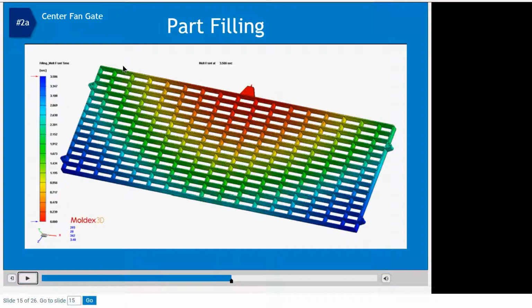Now we all know, if this cover is over, let's say, a safety hole or whatever, we have some mounting holes to put this grill over some safety area. So if the material is fiber filled and you have to have certain strength, the fiber orientation in this side versus that side through the fill pattern and through the ribs is really different. And as you know, fiber-filled materials shrink differently in the direction of flow versus perpendicular to the flow. So you're ending up with a very complex 3D fiber orientation challenge in this very simple grid part, which then can cause shrinkage differences and warpage potential.